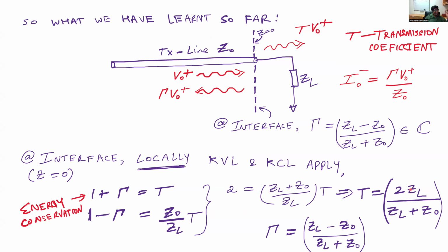We want to design a link in such a way that the link characteristic impedance is matched to the impedance at the load side, so that a minimal amount of the incident power is reflected and most of it is transmitted to the load. This is analogous to circuit theory, where it is just maximum power transfer.